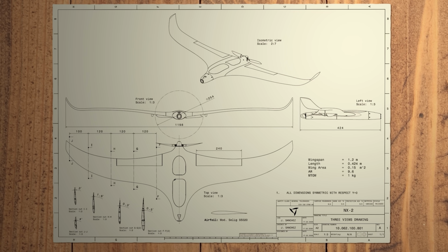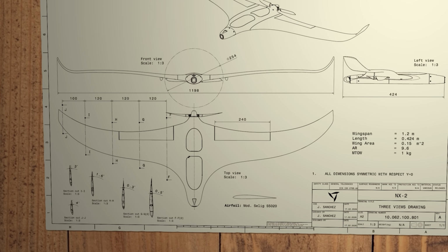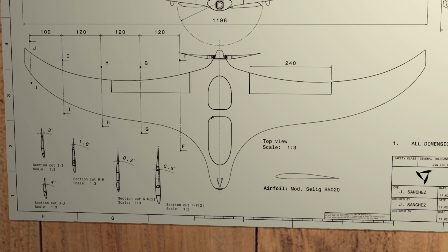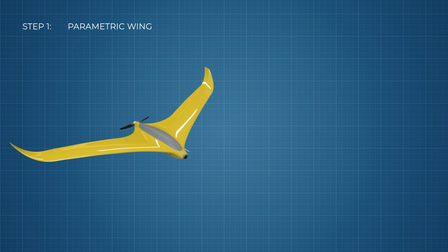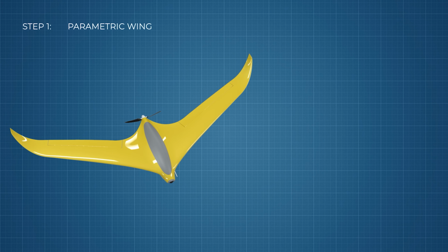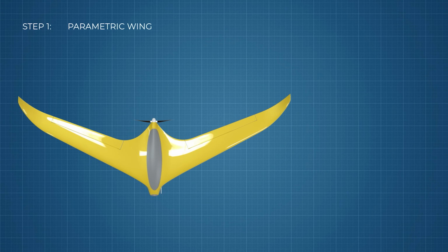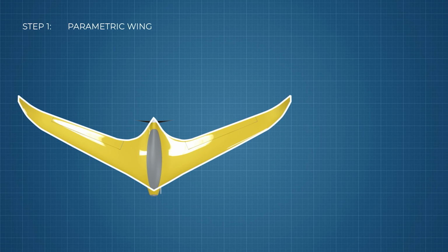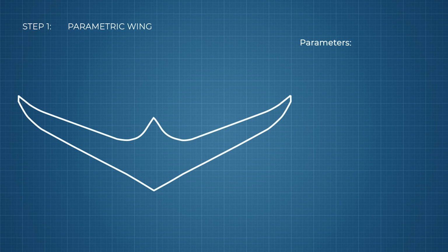So here I wanted to take a different approach, since to give our wing real design freedom I needed way more parameters. Let's use my previous wing as a reference, and I'll show you how I defined the entire 3D shape using 16 design variables. If we start from the top view, the wing planform, the first thing I control is sweep. One parameter sets the leading edge sweep angle, basically defining the wing's main backward arrow.